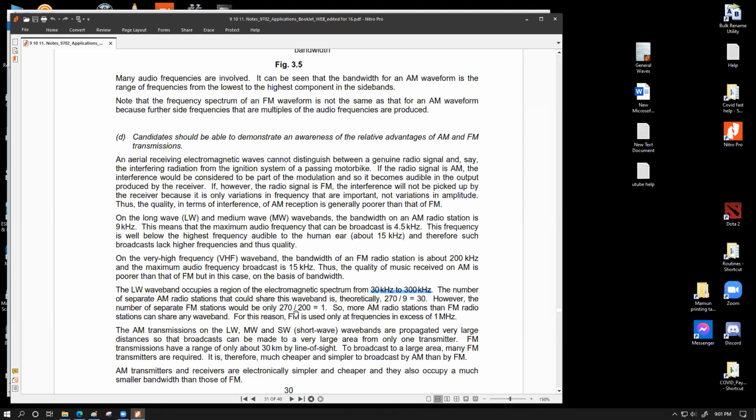This is the typical preference, but practically the preferred carrier frequency values for FM stations start from about 85 megahertz. Now, one pretty important thing: you might find that the radio stations in our country are one at 85.0 megahertz, then 85.4, then 85.8. Do you know that we have a variation of 0.4 megahertz? Anyone?